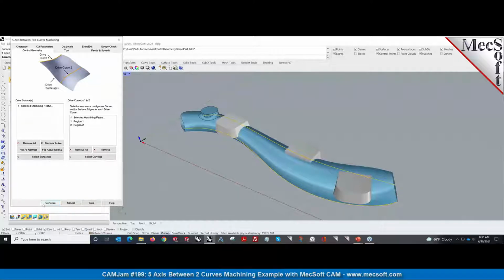But in 5-axis mode, apart from the X, Y, Z coordinates that we obtain from slicing, we also have the surface normals we use to actually position the tool along that surface normal. And then obviously there are some additional controls you can use to control the angles and the axes of the tool. To define that, you have to have a surface. So the surface basically gives us not only the coordinate points, X, Y, Z points to position the tool to, but it also gives us the tool axis vectors to use to position the tool.